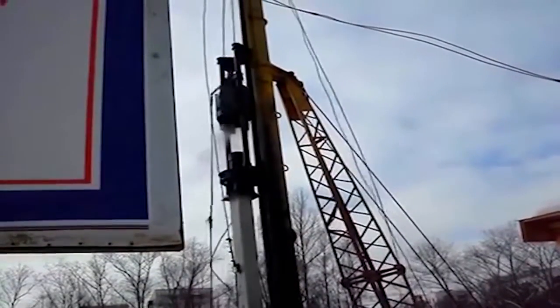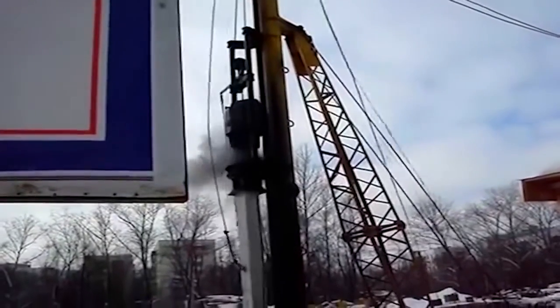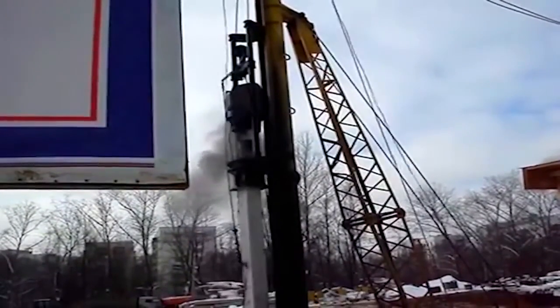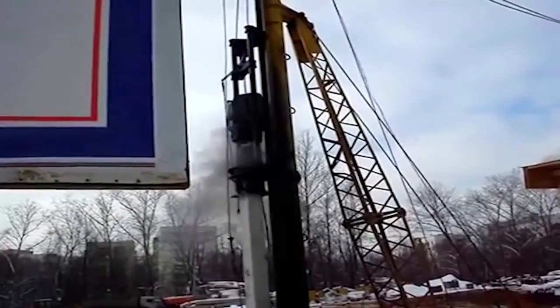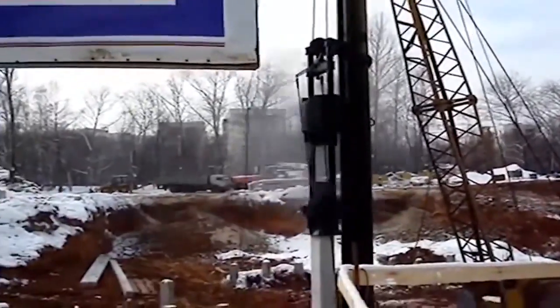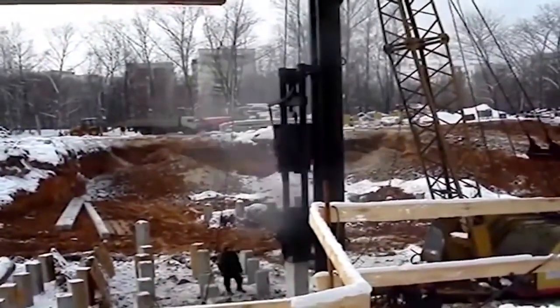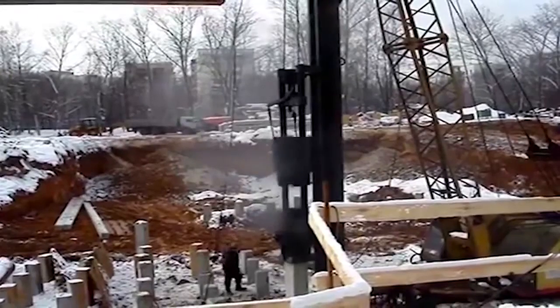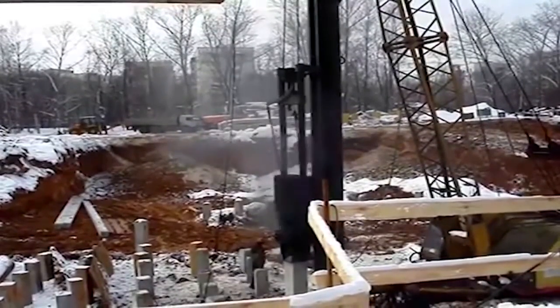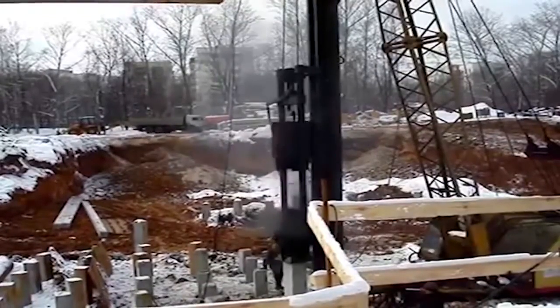Displacement piling is a hammering process, as you can see here. In this process, the pile is precasted and hammered into the ground. At present, displacement piling has been abandoned by the contractors as it has a few disadvantages such as high sound and vibration effects. Therefore, nowadays piling contractors use replacement piling instead of displacement piling.